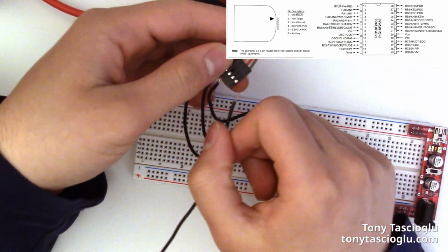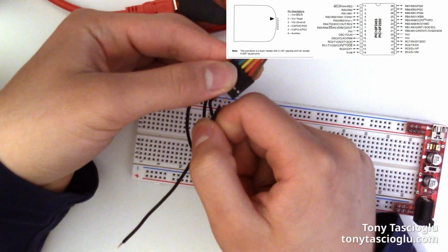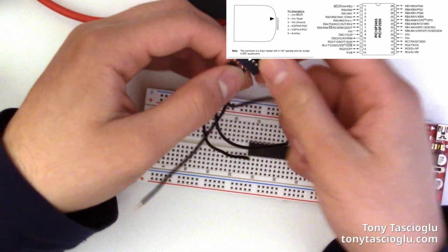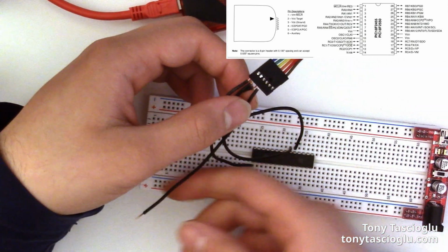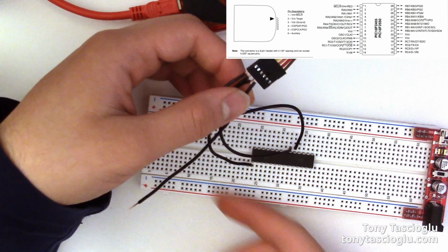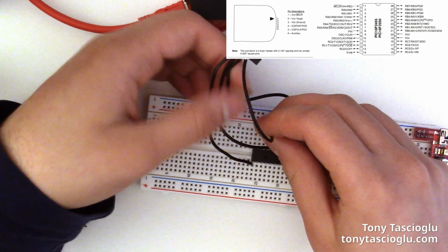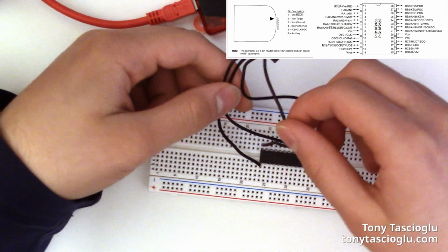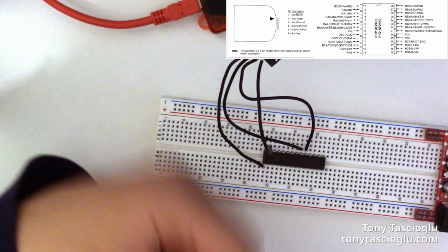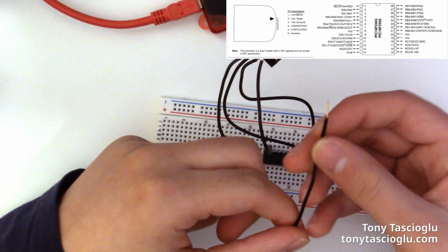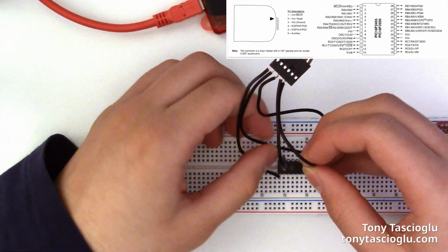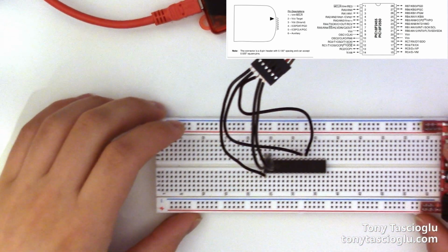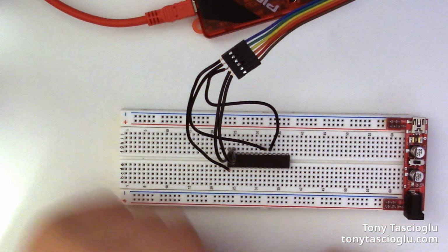Pin 4 goes to the ICSP data pin, also referred to as PGD. On our IC, that is going to be pin 28, which is over on this end. I've been trying to avoid having overlapping wires, but I think you guys can still see this. And finally, we'll connect to PGC, just like this. Now we are ready to actually upload a program.